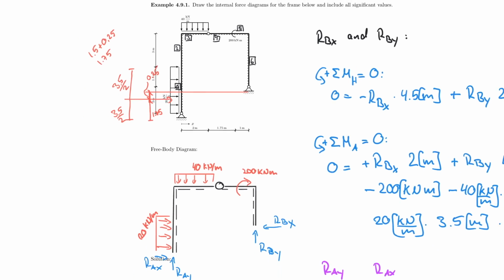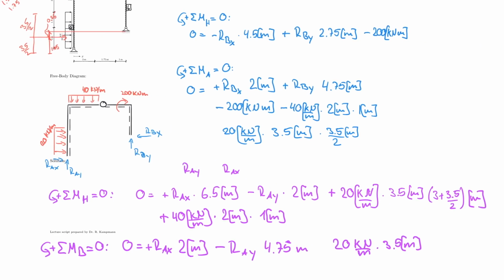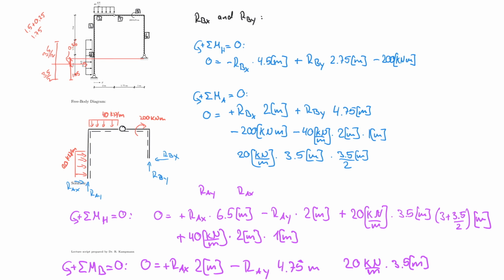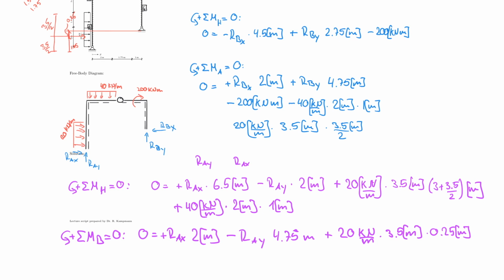So that means that our lever arm is actually 0.25. That is a little bit tricky, so that's why we're solving this problem, but my lever arm is 0.25 meters. And it's below the support, so the resultant here is below this point, which means that we're rotating counterclockwise. So therefore this becomes positive. And now let's deal with the 40.